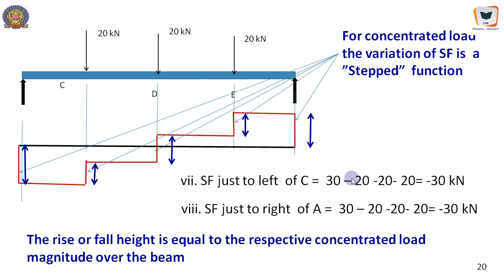Therefore, it is very important to remember that the distribution of shear force in case of a simply supported beam, or any beam subjected to concentrated load only, of course there is no mix of loads, it's only concentrated loads, is a stepped function with rise and falls of the step equal to the intensity of load just above.